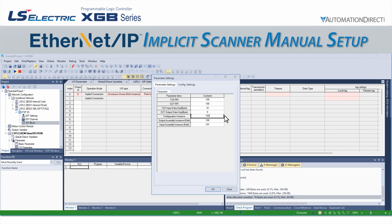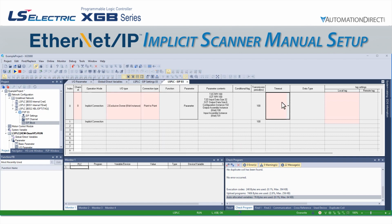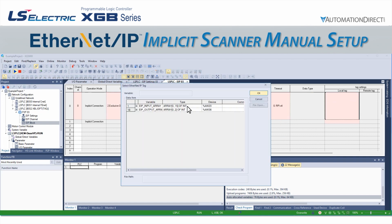The RPI will depend on the application and how fast of a drive response we need. If our RPI is too fast, the network will have problems keeping up. If it is too slow, the system will not respond to our commands as quickly as we want. We can leave our RPI at the default of 100 milliseconds for this application. Once we have completed our parameters, we can then set our timeout and add the arrays we created to the input and output lines of the message.